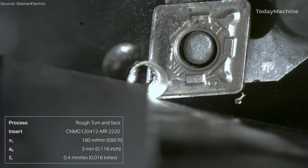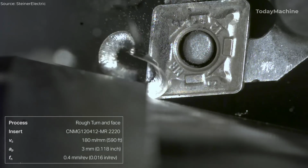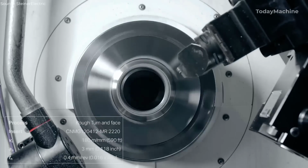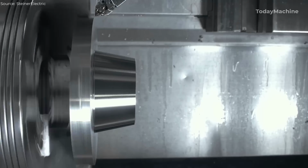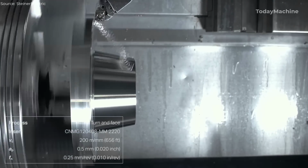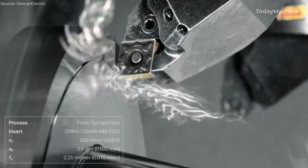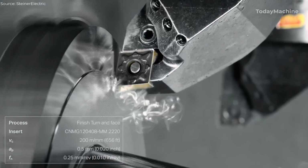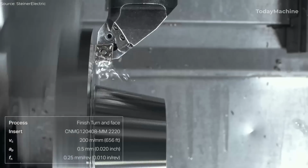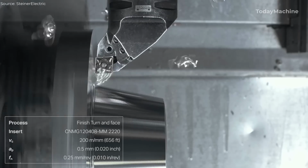A key feature of the GC 2220 is the Enveo coating, which enhances wear resistance and extends tool life. The coating consists of tightly packed, unidirectional crystals that form a robust barrier between the cutting zone and the chip. This barrier significantly reduces the amount of heat generated at the cutting zone, leading to improved crater and flank wear resistance. As a result, machinists can expect longer and more predictable tool life, which is especially important when working with materials like austenitic and duplex stainless steel.